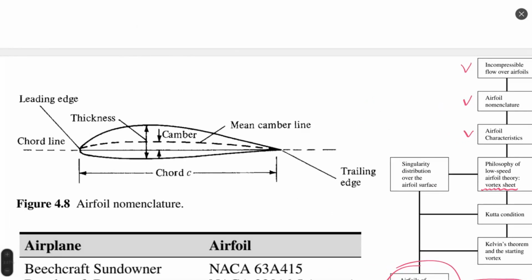It is so much cambered that most of the geometry is above the chord line. So it is a thin airfoil, but the upper surface of the airfoil is more like other thick airfoils. So how much is this actually positive to the thin airfoil?